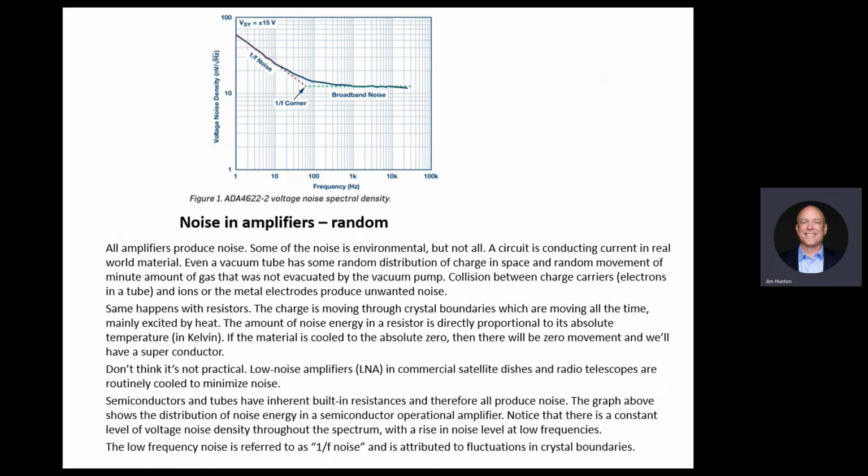If you're at the input stage of a phono stage, you have a lot of amplification ahead of you. Any noise there will be amplified a lot. You really want to use the best devices you've got. That's why we see a lot of JFETs in there, okay? And when you go to tube amplifiers, you get more noise. They're inherently, like a 12AX7, inherently higher noise than a JFET for the same level of amplification.